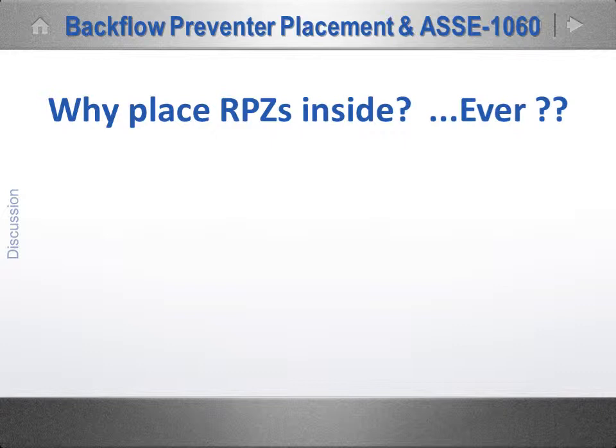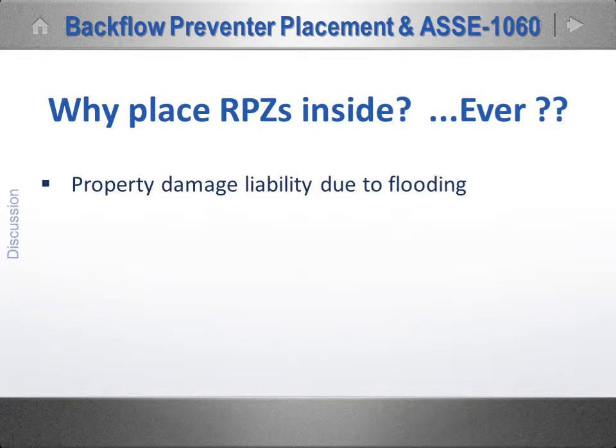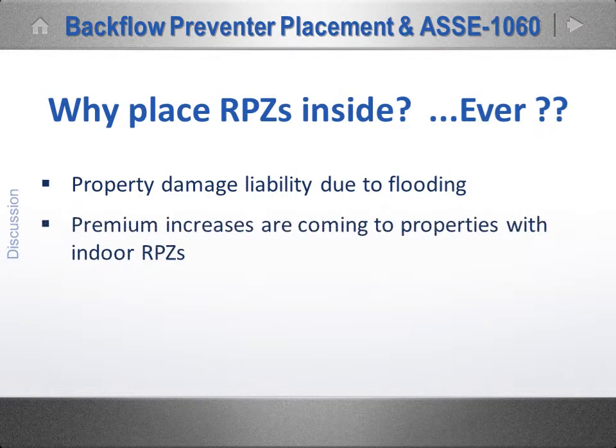Okay, so now for the second hard question. Why place RPZs inside? Ever? Unless extraordinary drain capacity systems are employed, larger devices bring significant property damage risk to any project. And given that reality, insurance premium rate riders are close behind.